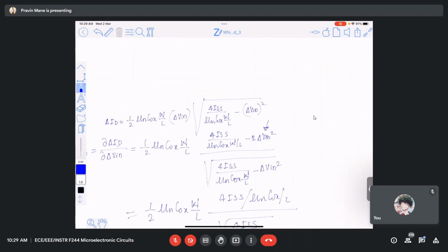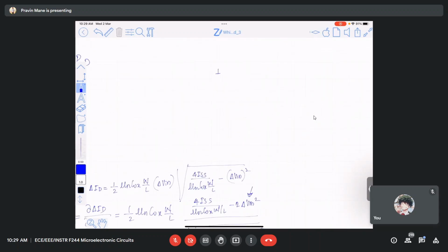Can you tell me what is the equation that I got for ID1? ISS by 2 plus ISS by V overdrive into VID by 2.